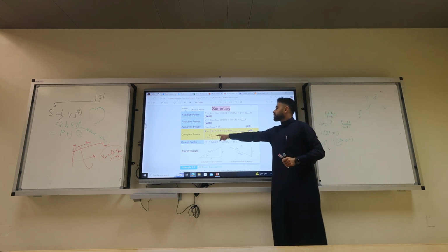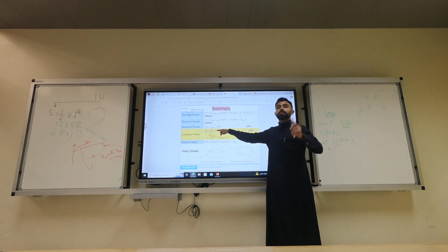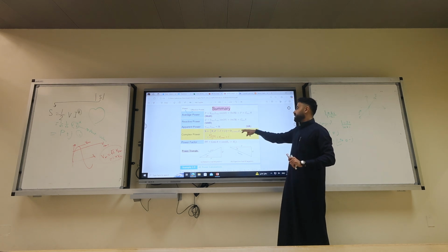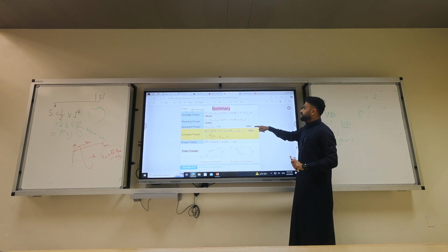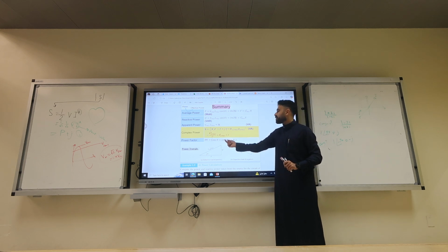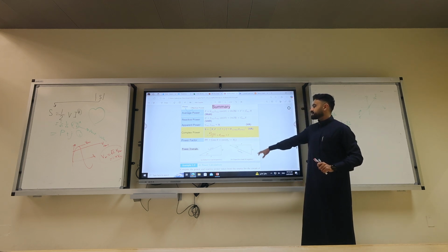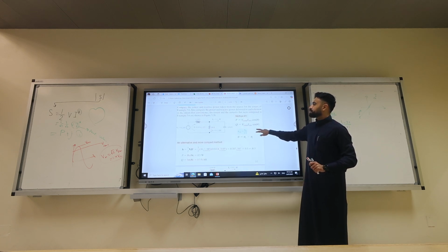Then we talked about the complex power, which has this formula. Again, this Vs and I conjugate are the max. They're not the IRMS or VRMS. S is what? Source. The units are watt, var, VA, VA. The power factor has no unit, which is cosine of theta_V minus theta_I, and that is the power triangle. Example. Let's do this example.